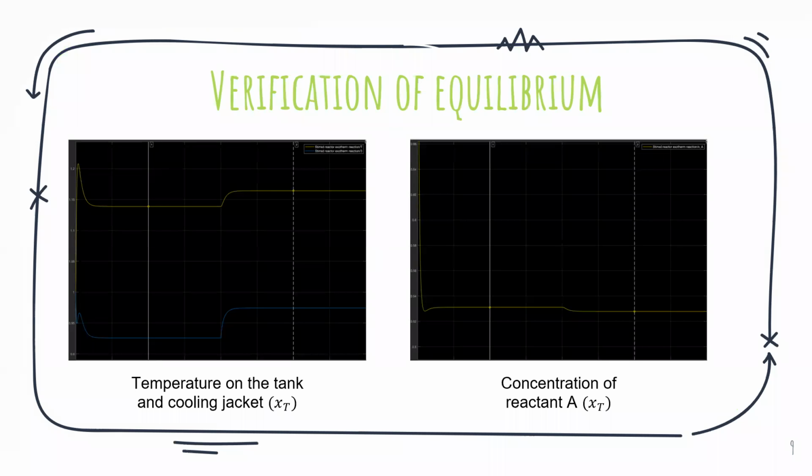Continuing with the equilibrium, when we run the model, we can see that all the values previously calculated are indeed the same as the results of the scopes as seen in the next images. As I previously mentioned, the values of the variables are now seen in these plots. On the graph on my left hand, the temperature xt is 1.139 as previously expected. And from the graph on my right hand, we can see that the value of the reactant XA is 0.531.